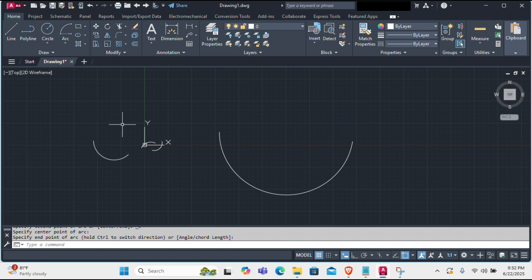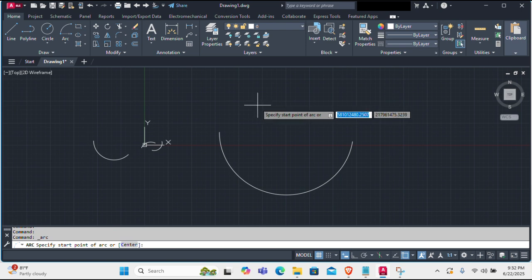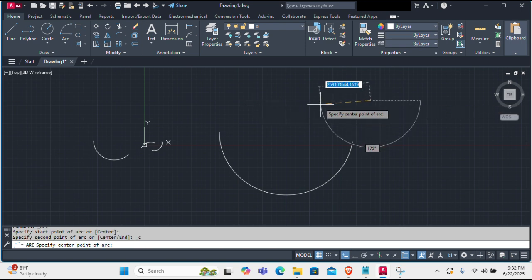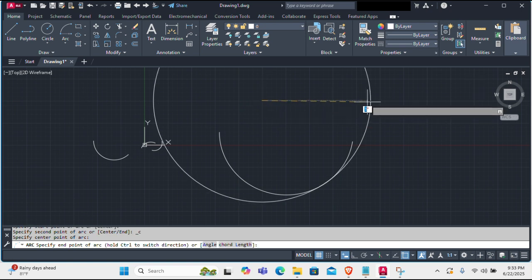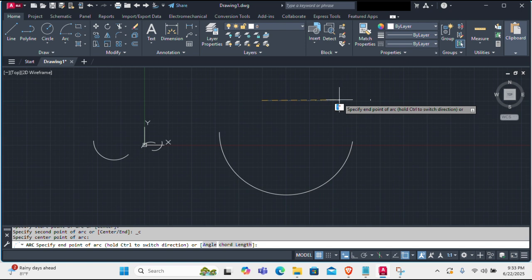So when you go left to right like this, this point will be my start point, which I will be moving to make my arc, and this point will be the center point. Now imagine you are holding a compass and drawing on paper. Now click on it. Now this will be the other end of your compass, with the pencil.